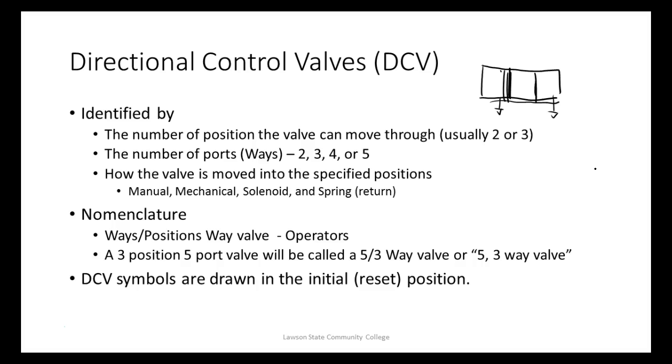So a two-position, four-port valve, we'd say a four two-way valve. That's the way you would order them. That's the way you would say it. So you don't see anybody that's been working on it that would say a four-port, two-position valve. You don't hear anybody say that that hadn't been in the field there. And if you looked up and you ordered them out of a catalog, they wouldn't be that way either, right?